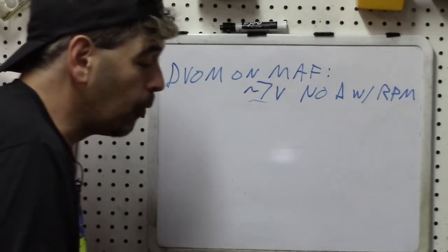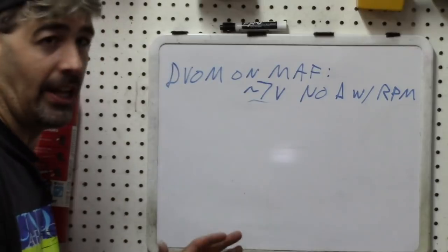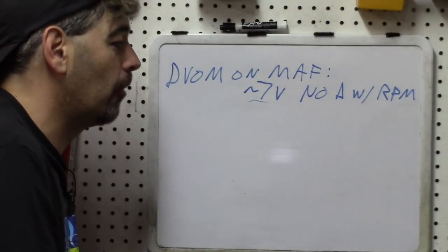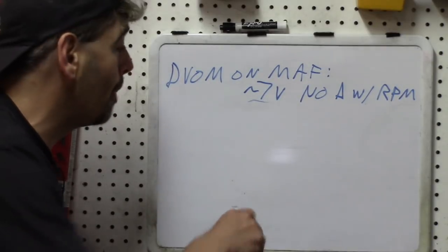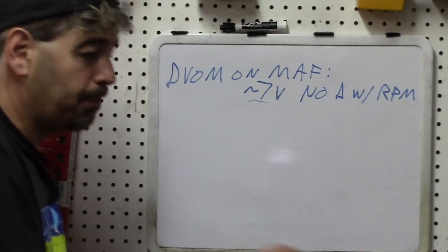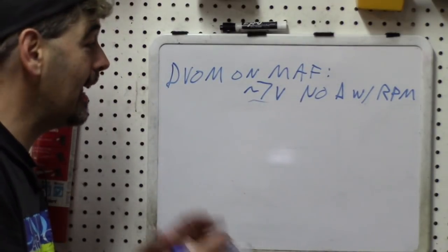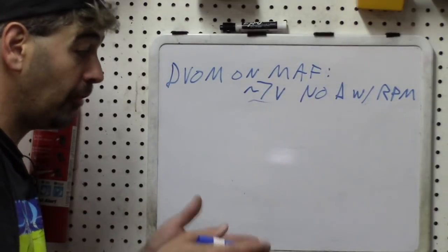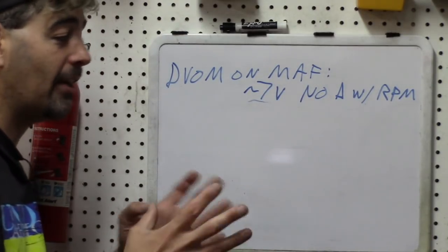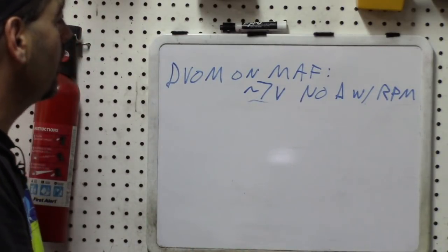And another choice was that the signal wire was grounding out. That makes no sense whatsoever. Hopefully you didn't choose that. If you did, you'll want to look back at some other videos with some more basic electrical foundation. And of course, the third possibility was a bad MAF sensor. No conclusion could be drawn on that in any way whatsoever. As a matter of fact, no testing on the MAF sensor itself was even done. Only testing for the feed to the MAF technically was done. So hopefully that makes it clear to you.